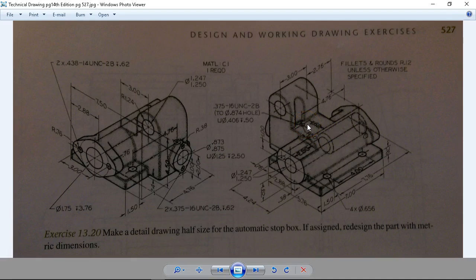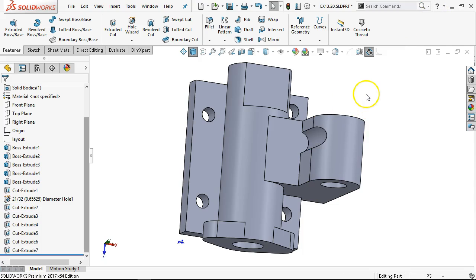1.2 to the 1.62 to the center. Well, there is a possibility that 0.875 is missing its depth call out, and the 1.25 counterbore is actually correct. All right, so 3/8, half inch. We'll see what they're doing on these call outs.